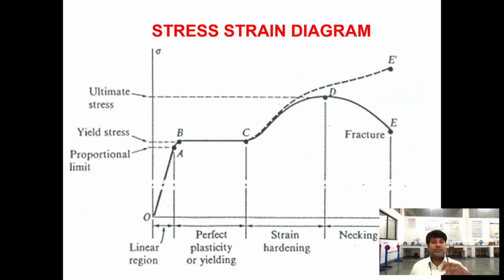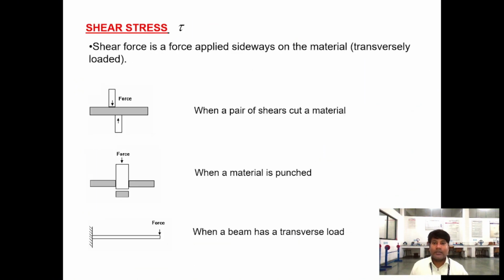Necking means you will see the neck, so you will see that the diameter of the rod will decrease, and then after it will fracture. Now, the next topic is shear stress. Shear stress, what does it mean? It is a force applied sideways to the material.